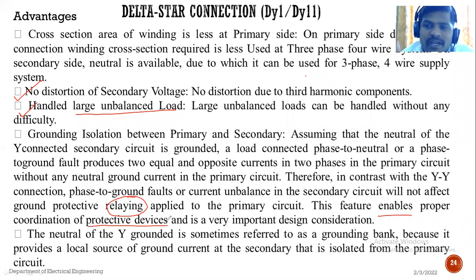Okay, so there are multiple protecting devices that can be used. That means we use the MCB, the circuit breaker, and some of the relaying equipment. There are multiple protecting relaying equipment. Suppose for earth fault protection, for ground protection, for transmission line protection, for transformer protection, there are multiple types of switchgear equipment that can be used. So for earth fault protection, an earth fault relay can be used.